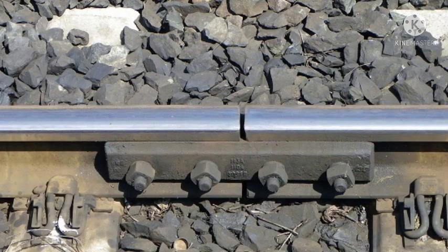When these two rails are joined thus, there is a gap given between these two rails, and you have learned from your primary classes that this gap is given for giving room for expansion of these iron rails. Iron rails get expanded during summer. Both rails will meet each other during summer. So if the gap is not given, there is a chance of the rail bulging at the joint, and there is a chance of derailment. In order to avoid this problem, the gap is given.